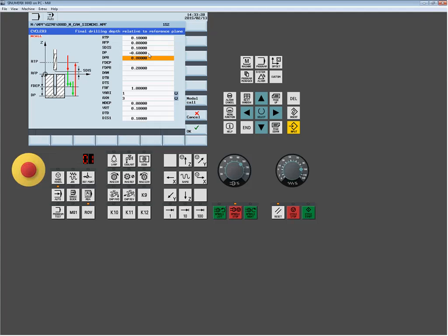You do have to remember that procedure, however. You've got to make sure that you go to Program Manager and highlight the file wherever it exists. It could be on a network drive, it could be on RS-232. Hit the execution button. External execution is what it stands for, EXT execution. And then cycle start and start running the program.